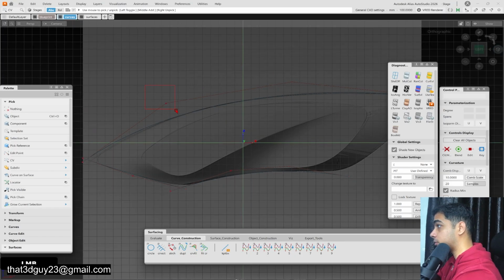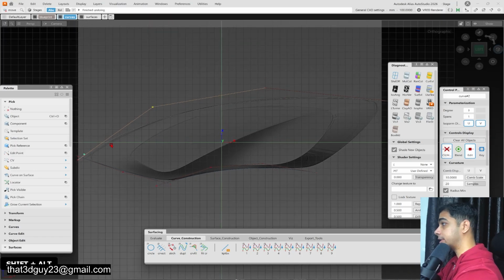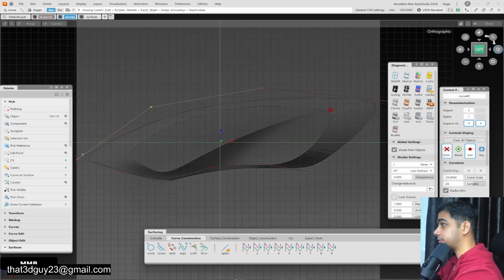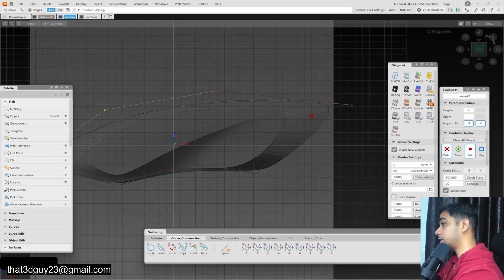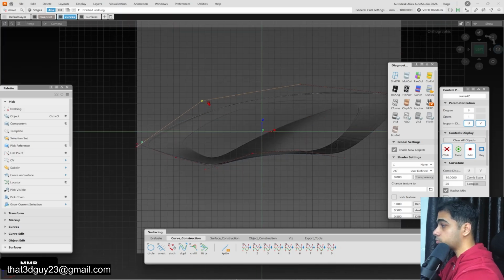If I want, I can obviously have this a bit exaggerated and have it in a ratio of 1:2, 2:3. I can also have it in the ratio of 1:1:1. That's perfectly fine. Depends on what I'm modeling. If I want to have that aggressiveness, I'll have a ratio of 1:2 or 1:2:3. If I want to have that subtleness as a product, I can have it 1:1:1, right? So that is what I mean. So basically what I mean here is the space between the CVs are in the same ratio.